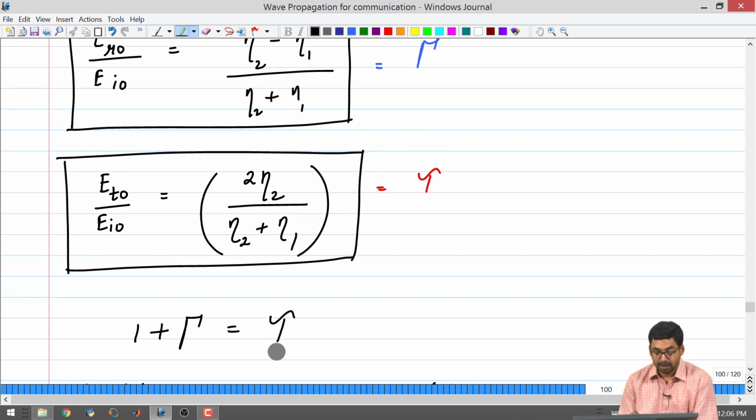This means that the transmission coefficient can be greater than 1 when we are talking about the value of the electric field, alright. So, it means that your incident electric field can be 1 volt per meter, and the transmitted electric field can be higher than that, but it does not mean that energy conservation is violated. Whenever the electric field goes up in the second medium, the magnetic field will proportionally go down to make sure that the conservation of power or energy is held correctly in the system.